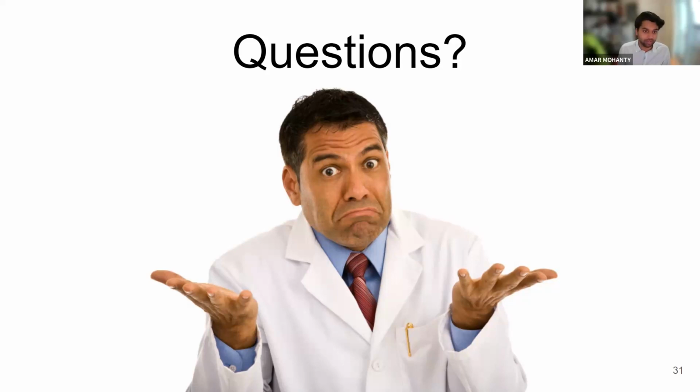But what we envision is that you could have an at-home assessment that roughly tells you if you're at risk, and then in a more clinical setting, which is more standardized, where they can afford a little bit higher upfront costs with IMU sensors, and someone who's trained, you can get fairly accurate pose estimations, we think, by adding these IMU sensors, which are only a couple dollars each. But really the issue is getting the wireless communication and syncing and making sure everything's calibrated. So those are the big challenges where we had to do some more complicated workarounds, but it does allow for a lot more opportunities, as Zach pointed out.